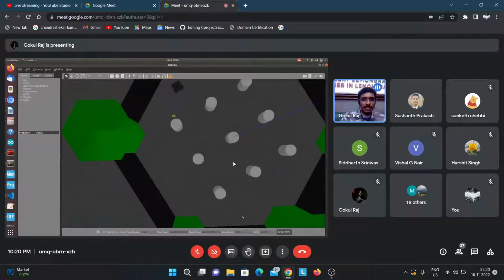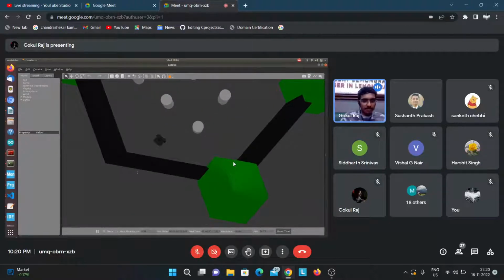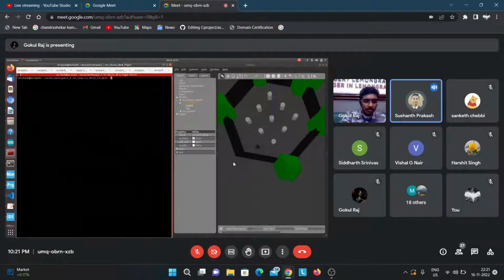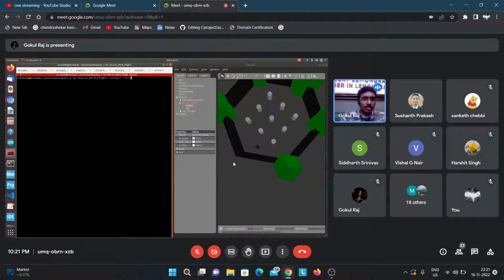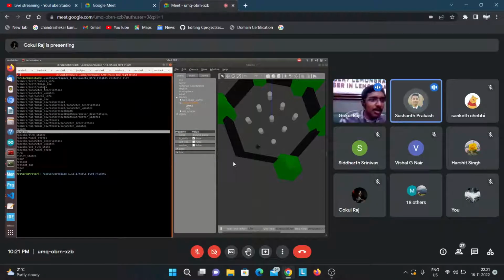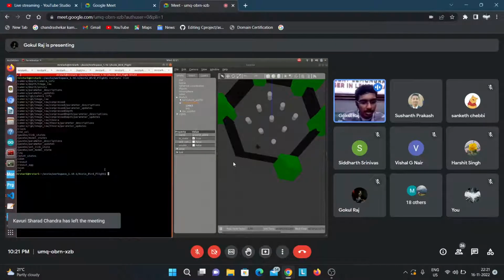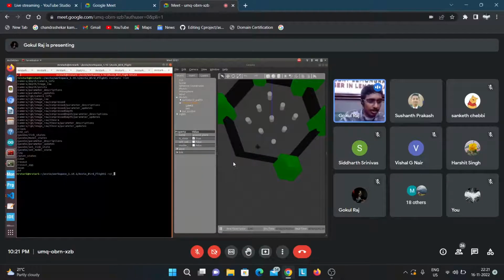So you can see here there's this mobile robot. Now similarly, let's see what all the topics are that this mobile robot publishes. Are you controlling it with the ROS app on your phone? We can do that also. I'll first show you all the topics. ROS topic list will give you all types of topics. I'll just give you the basic commands. This is basically to control the velocity. This image one is basically the camera. So let's see, first I'll show you RQT graph.